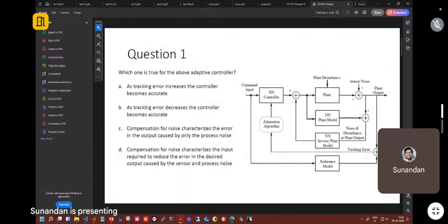Yes, we are sending that to the inverse plant model, and with that the inverse plant model is telling me what the noise and disturbance at the plant output is. The NN-based plant model is not modeling the noise, so whatever deviation is happening due to the noise should practically come here, and the inverse plant model is trying to find out how much I should change the input so that I can achieve the desired control output.